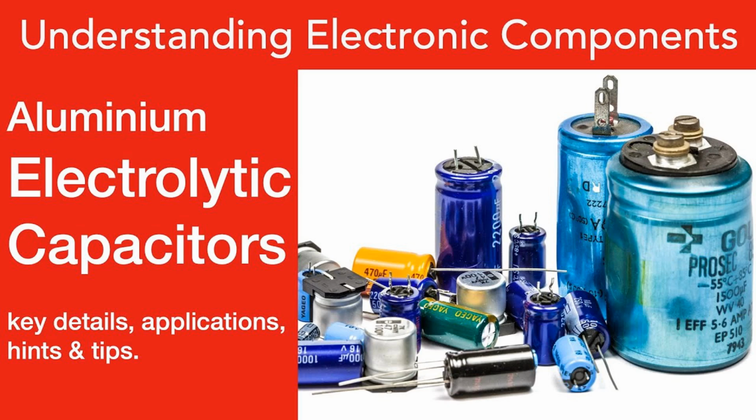High-frequency signal decoupling. Capacitors are used to decouple high-frequency signals in RF circuits, ensuring that the high-frequency components do not interfere with other parts of the circuit. Example: in RF amplifiers, decoupling capacitors prevent unwanted high-frequency noise from affecting the performance of the amplifier.